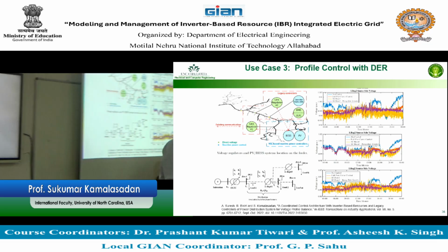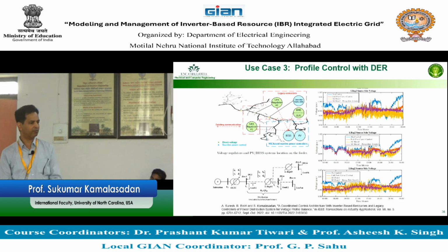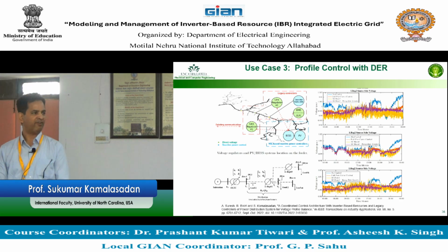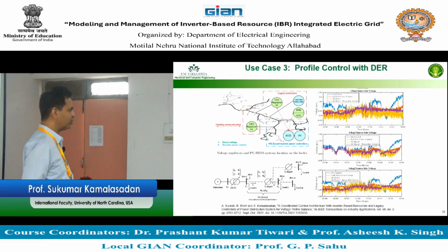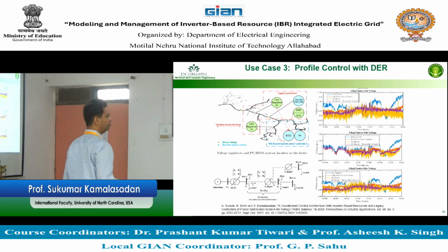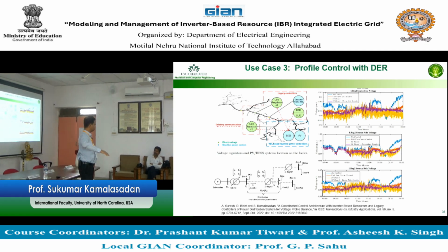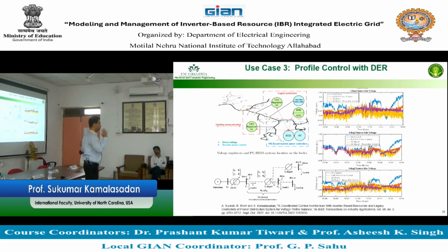Okay? So utilities normally use hydropower plants, peaking power plants, and fast gas turbine plants to ramp up that fast. So this is the ramp rate problem, or ramping up problem. What you have to do for that is make sure that these devices can move fast to control this duck curve. Are you following? Okay.